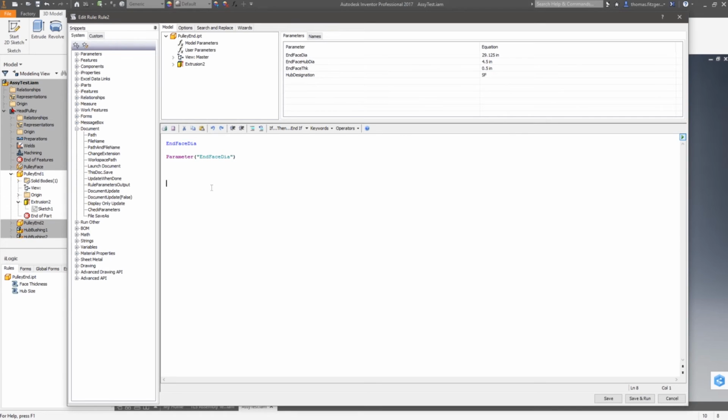You don't want it to be a recognized parameter inside of the rule, because iLogic will say, this is a recognized parameter, you've changed it, now I'm going to run this rule. And you may not want to at that particular time, in which case you'll use this format instead. This is still a parameter, we're still accessing the parameter, but iLogic doesn't want to fire the rule by default by having this in. So they do the exact same thing, they're still accessing the parameter, however, one is recognized, one is, we're just making a call to it, and it's not monitoring this parameter.